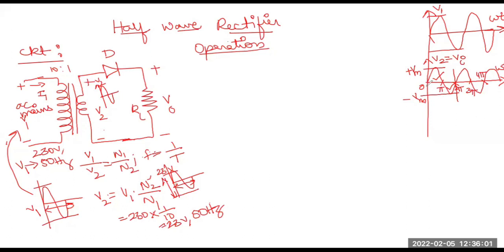Is that clear? So we are going to take the time period as one complete cycle because it is periodic in nature, the shape is not getting changed. So periodic for every time period T. So here what is the time period T equal to? It is equal to 2 pi. Isn't it? For every period of 2 pi, the waveform is repeating itself. That is how we define time period. Time period is the period for which the waveform repeats itself. So here the input waveform is repeating for every 2 pi period, so the time period for the input signal is T equal to 2 pi.